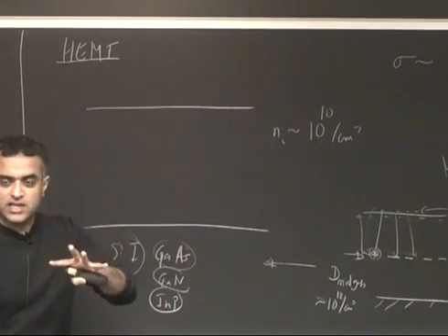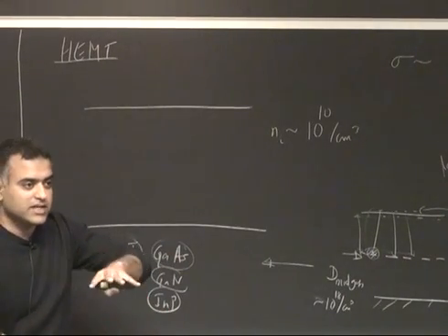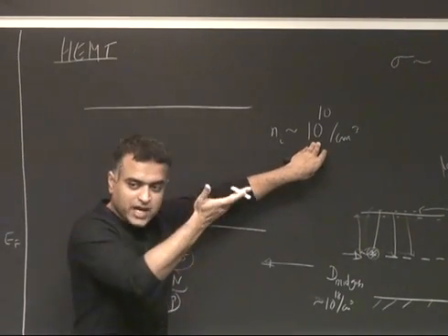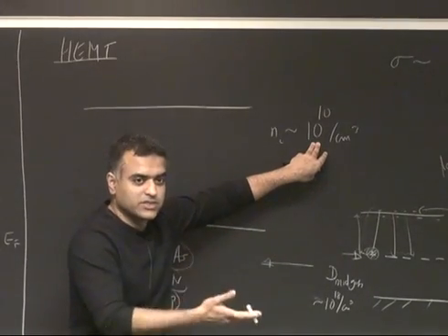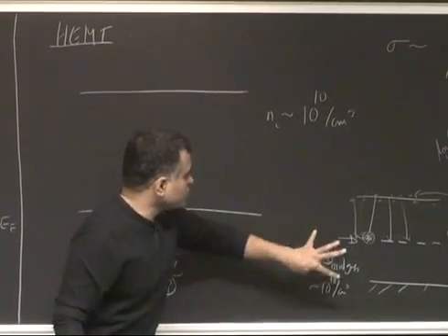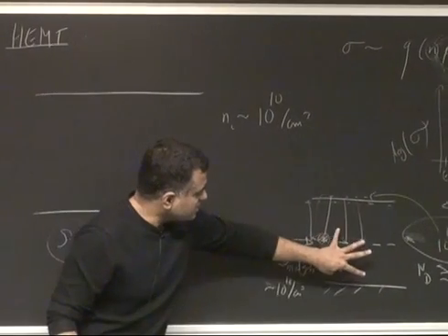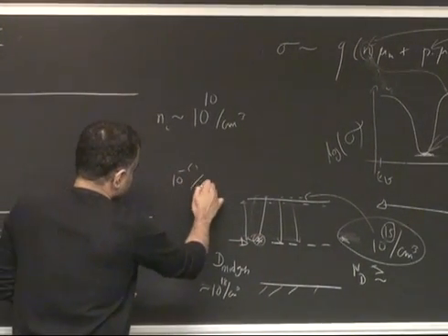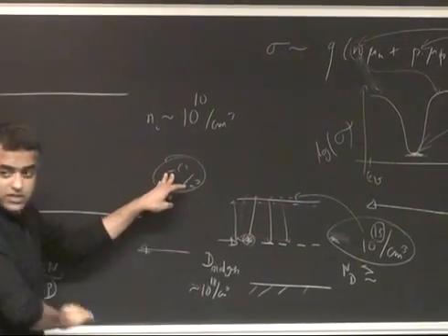This is the intrinsic carrier density, thermal generation, purest. Any little deviation, you put in some dopants, your carrier density will always be higher than 10^10 per cm^3 at room temperature. But if you do something like this, the semi-insulating, you can basically go to 10^-something per cm^3, which means there's nothing left, all the carriers are gone.